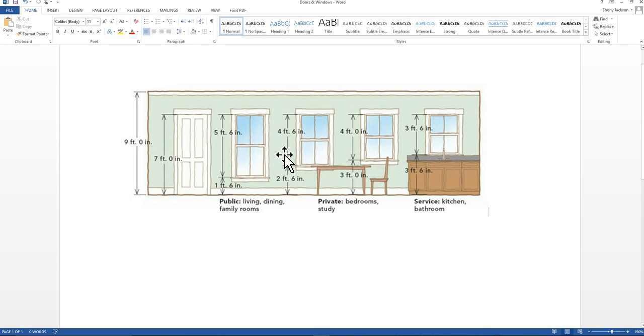In that illustration, we wanted our window to be 4 feet 6 inches going up in height, and we wanted that 3 feet to be the length across. It can get kind of confusing when you're putting in those dimensions. You always want to make sure that you put in your width, which they don't specify as width, they specify it as length in AutoCAD.